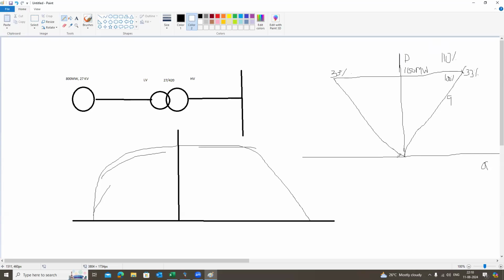For that, we will take an equivalent network and draw the PQ curve. That means for 100 megawatt, this value is 33 MVAR, and here it is minus 33 MVAR. For different grid voltages, with the help of the inverters, you will validate whether you are able to maintain 33 MVAR on the lagging side and 33 MVAR on the leading side.